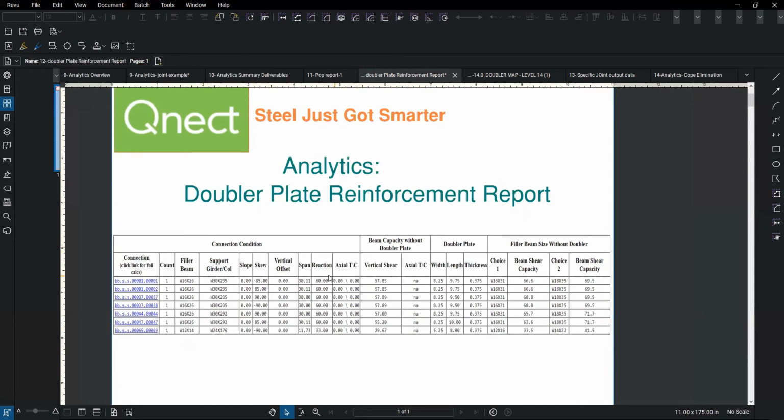As you can see here, the connection is for 60 kips, but it's only good for 57. Now, not a big gap, but sometimes it's much larger, 33 to 29. The fact is, you can't just use 57. You'd have to get permission. And this chart allows you to identify where in the plan, send an RFI, ask the EOR to reduce it.